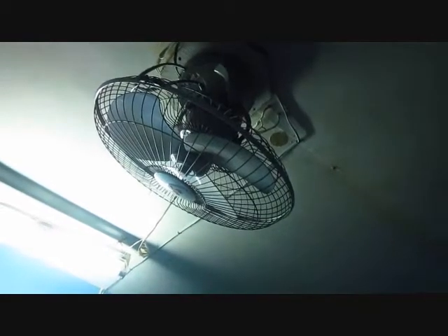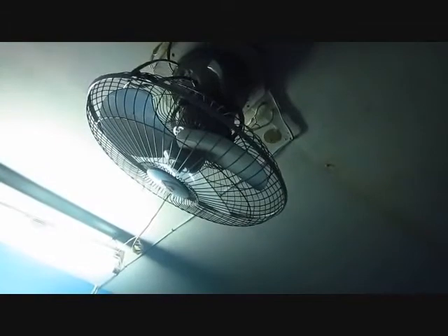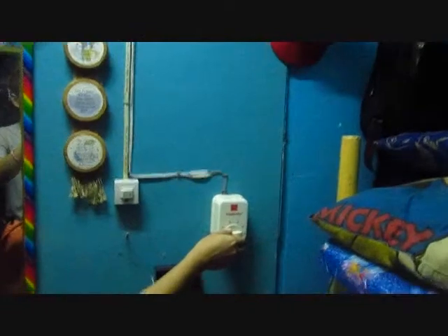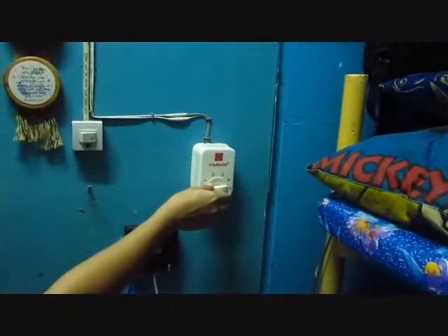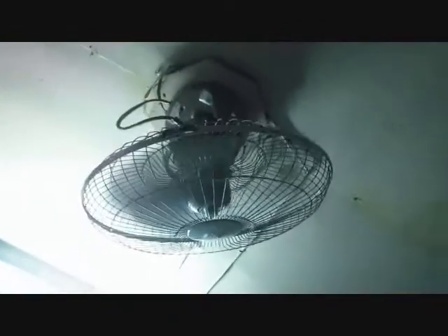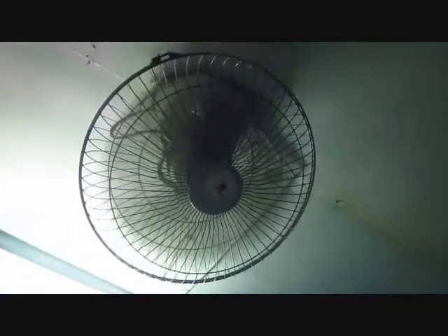The industrial loads are composite loads, and induction motors form a high proportion of these loads. These composite loads are functions of voltage and frequency and form a major part of the system load. Commercial and residential loads consist largely of lighting, heating, and cooling. These loads are independent of frequency and consume negligibly small reactive power.